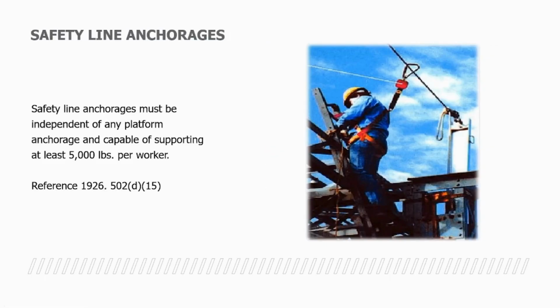Safety lifeline anchorages. Safety lifeline anchorage must be independent from any platform anchorage and capable of supporting at least 5,000 pounds per worker. You can reference that to 1926.502 D15.